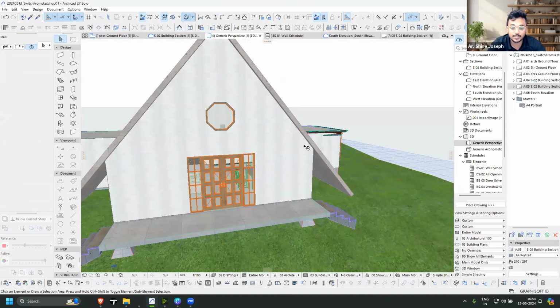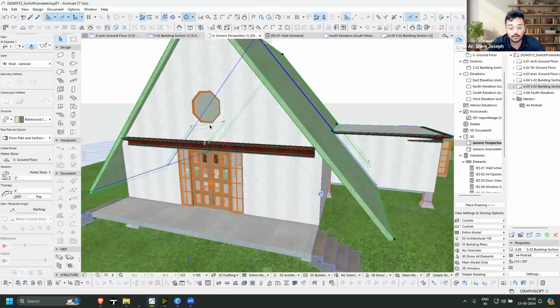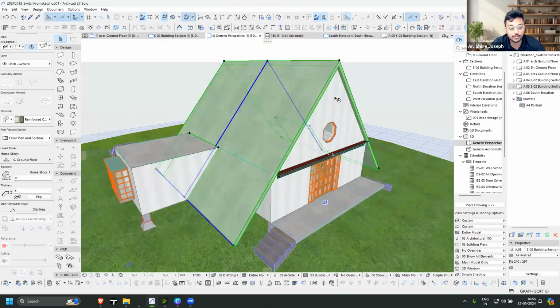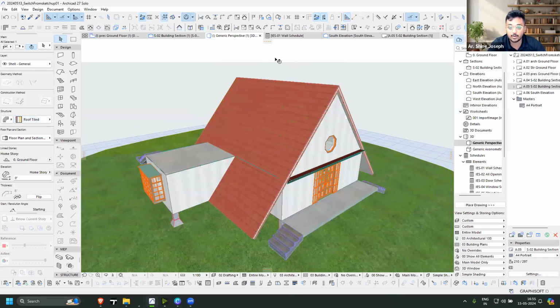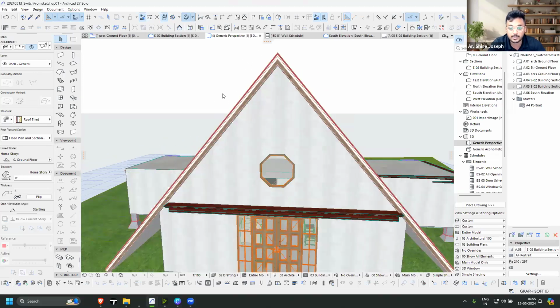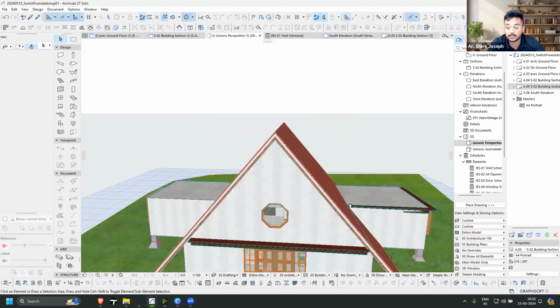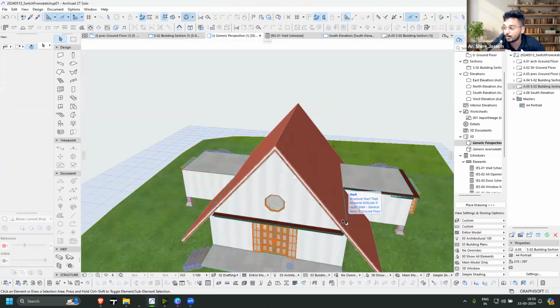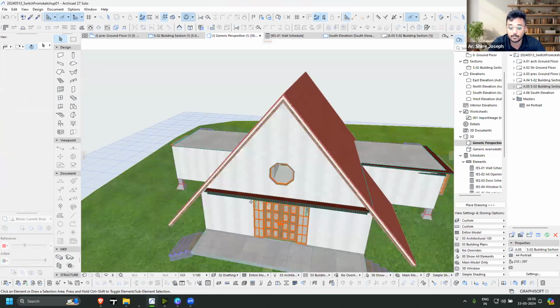So this composite helps us really better when it comes to all these things. In this, we also added, if you remember, this roof structure with only one layer. I'm going to change it to multi-layer, and I'm going to take the tiled roof option, where now you will be able to see all these layers within this. So the advantage is this: we can define specifically how it is, where it is, what the dimension is, what material it is, how many layers there are. And now we are actually adding the LOD, the level of detail, to the model. So over the period of a project, when the level of development increases, this LOD value also can be updated